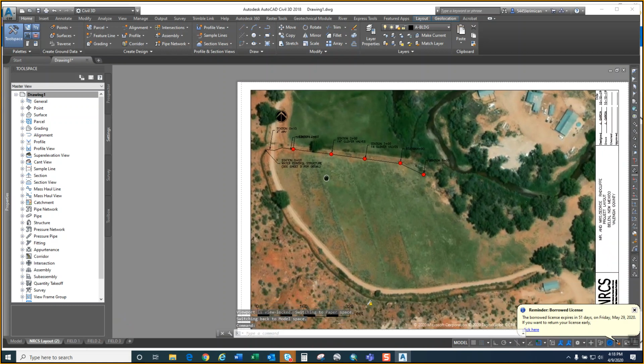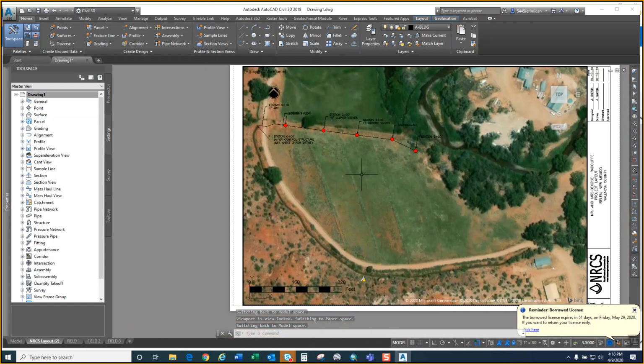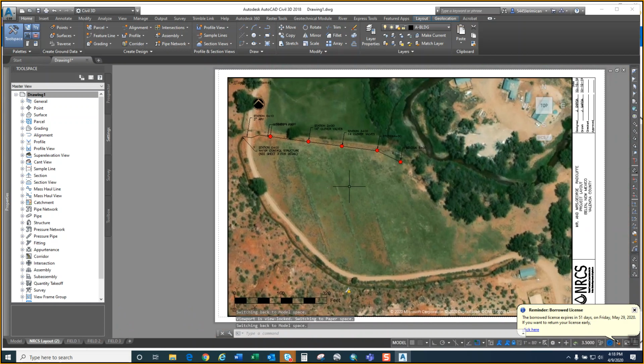All right. I also like to show the flow direction of the fields, even though it's kind of common sense where it's going to go. So what I do is I use the leader function, LAD leader. I want my arrow to start here and go up to there. Click enter. I don't want any. Click enter twice. When you click enter twice, it'll give you the option to not put any text. So click done. And now you have a leader or an arrow.